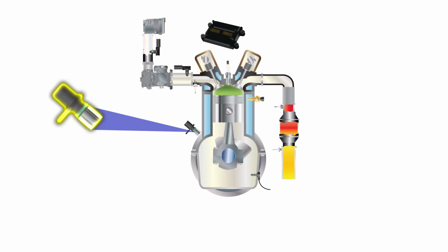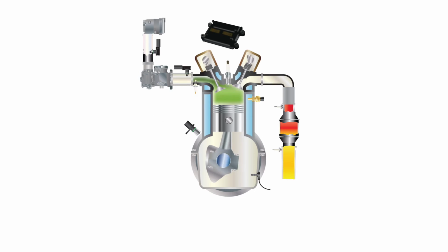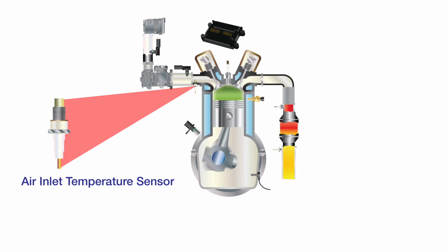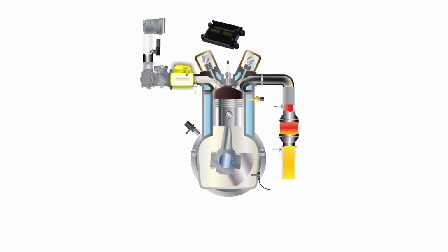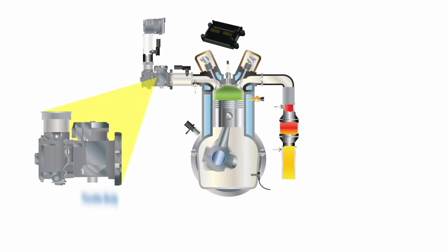Crank and cam position sensors are fitted to measure engine speed. The signal sent to the ECU synchronizes the ignition system to the engine speed. For example, if the load pulls down engine speed, the throttle will increase fuel. A sensor measures the temperature of the inlet manifold air and works with the coolant sensor to maintain a constant, even air-fuel mixture when the air density changes. This sensor senses the inlet manifold pressure for the ECU to determine how much fuel is required for ignition in any given cylinder. The ECU sends signals to the engine throttle body to change the fuel mixture to the engine.